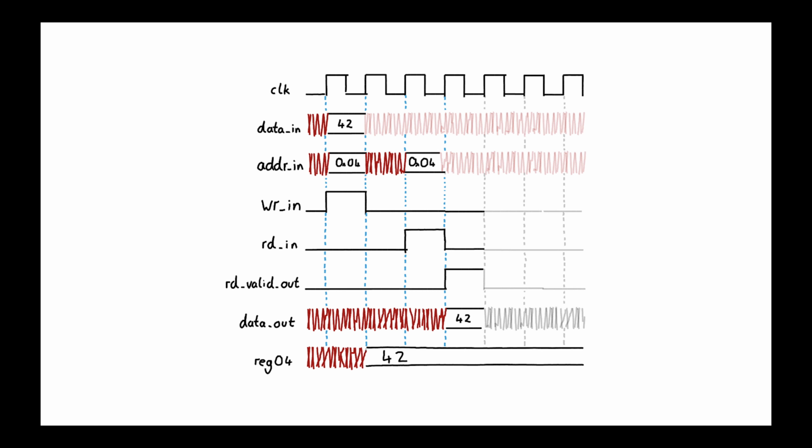This is a very basic interface, and it resembles the lite common interfaces used by Intel and ARM on their devices, such as AXI or Avalon. However, be warned that a memory mapped hardware interface might not always look quite like this. There can be subtle differences depending on the type of memory controller you are connected to. But this should give you a pretty good overall feel for what the interface looks like.